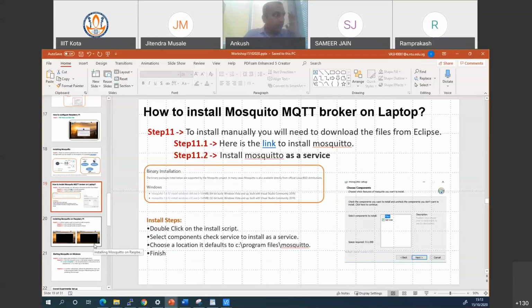So what we are doing at this step is trying to install Mosquitto. Why am I installing Mosquitto? Because I have to implement MQTT at the application layer. Why are we installing MQTT? Because we have to use that protocol for data communication from one machine to another machine, right? We have three machines now: two Unix machines and one Windows machine, that is my two Raspberry Pi and one Windows system.